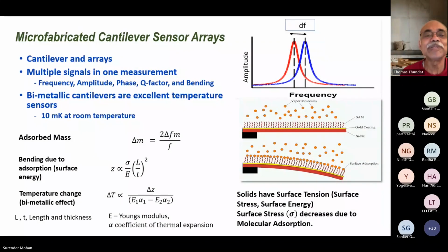So this is a simple microfabricated cantilever, shown in a little cartoon. They look like a diving board, and generally we make these into arrays, and to make it a chemical sensor, we always functionalize one of the surfaces with some selective agent like self-assembled monolayers or thin polymer layers or metal or semiconductor, any of those surfaces with a different chemical affinity for absorption.